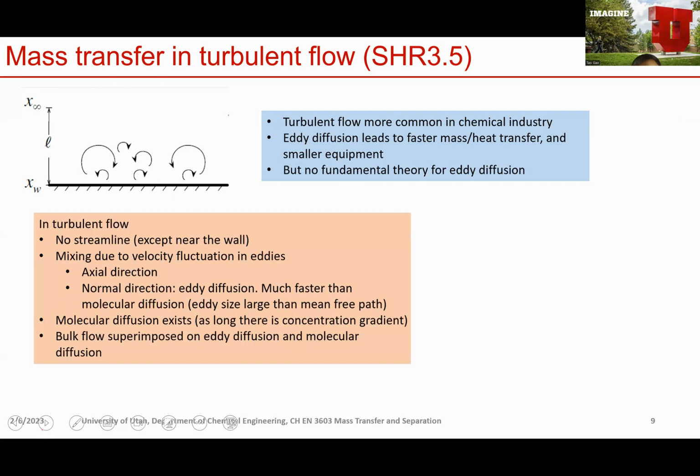So in turbulent flow, there's no streamline. There's mixing due to eddies because there are velocity fluctuations in the eddies. What is of interest is the normal direction mass transfer due to eddies, and that's called eddy diffusion. That is much faster than the molecular diffusion.